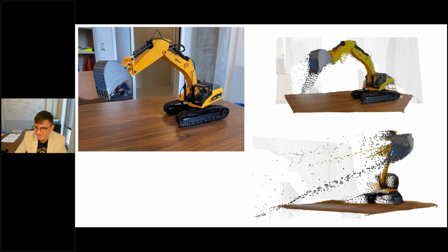So occlusions are shadows in the point cloud data. This is a big part of why it's important to have a scan plan, so that everything that you want represented in the scan is actually in the line of sight of your reality capture hardware. The mixed pixel effect looks like floating pixels kind of splashing off of the edges of objects. Most scanners do a pretty good job of filtering this kind of noise out, and it's only really severe here because I used a low-cost range camera to capture this.